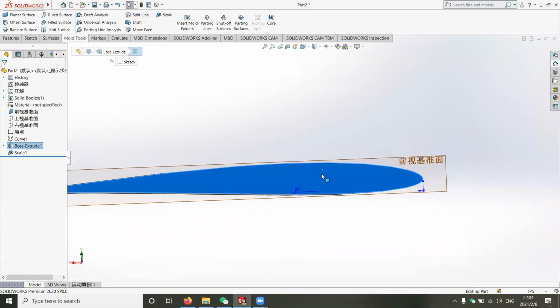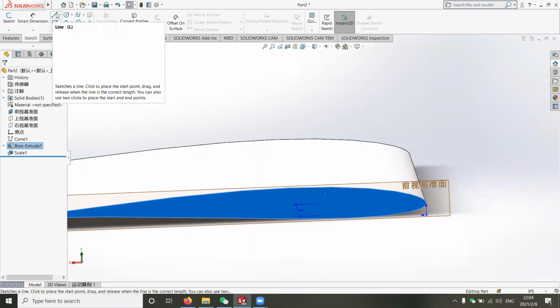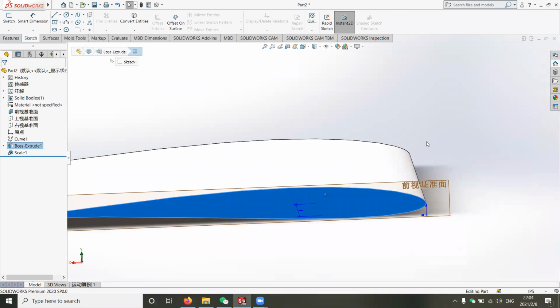I do know my airfoil is kind of thin. Some of your airfoils might be really thin too. So in this case, for the inserts to stay well in the wing, we need to make a little bit of modification. We do know that the wing should be mounted on the sensor centered at its quarter chord. So we need to generate 2 holes, one on the left side of the quarter chord and one on the right side of the quarter chord. This is a 4-inch wing, so the quarter chord is 1 inch. Okay, so I do know that my wing is small.